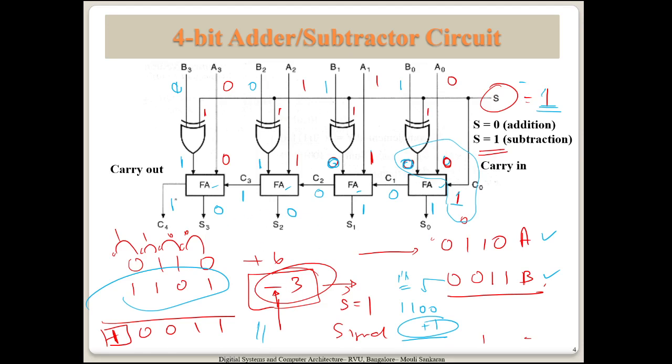This carry we are not going to be looking at because it's signed arithmetic. We are going to look at both the carries together and then find out whether the result has been correct or not. So if we are giving these two carries to an XOR gate, this will be an overflow flag, which is not set because these two are zeros. So this is the last two carries, and the result you have got is 0 1 1.